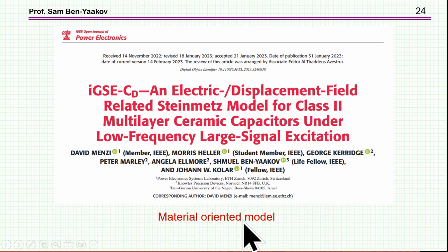In the ferrite case, we have, on the one hand, the Steinmetz equation for the loss of the material, and then we have some information about the structure of the core, and when we combine the two, we can calculate the loss. And in this paper, which is also about to be published, there is one step toward accomplishing this desired situation in which the model will be based on the material rather than individually on each unit.